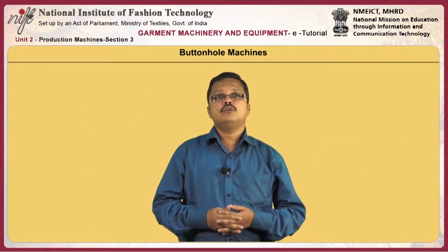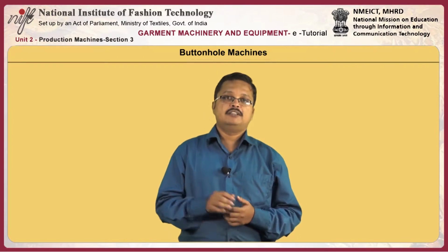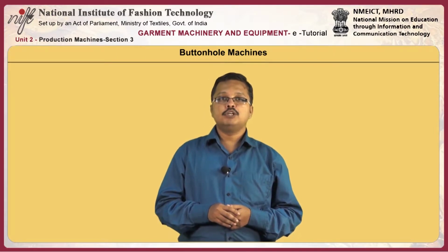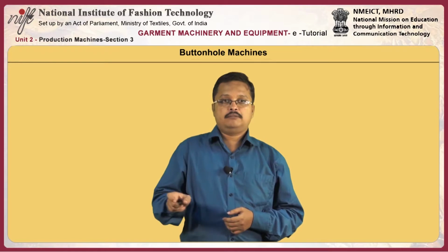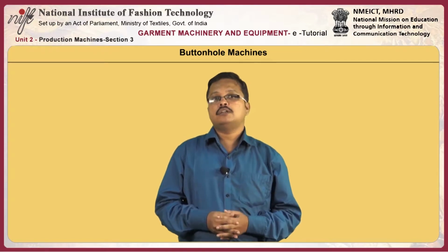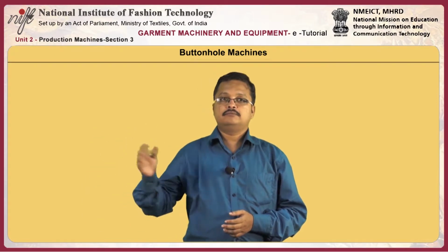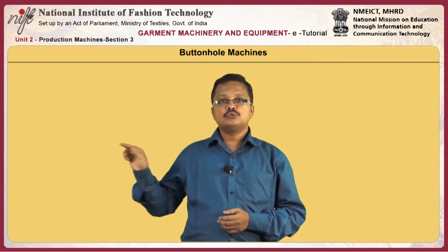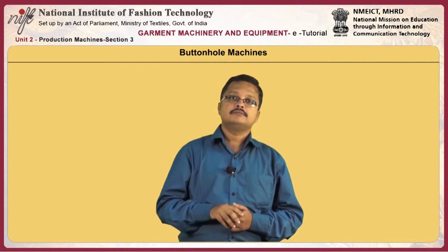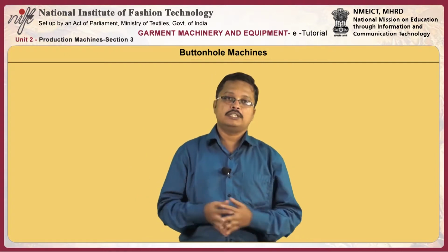Generally, buttonhole machines have a clamp feed, with the clamp being able to move in a horizontal plane. In a microprocessor controlled buttonhole machine, a console is provided on the side. The operator can use this to choose the pattern, stitch density and buttonhole size.